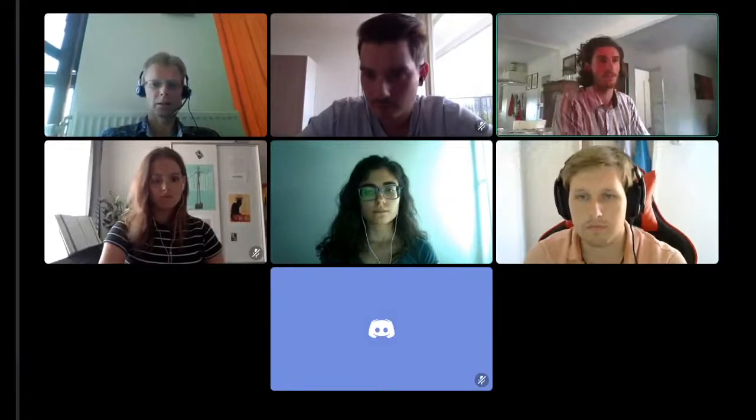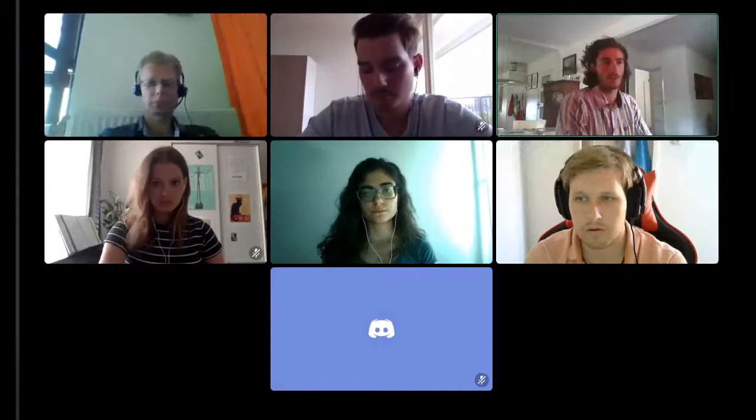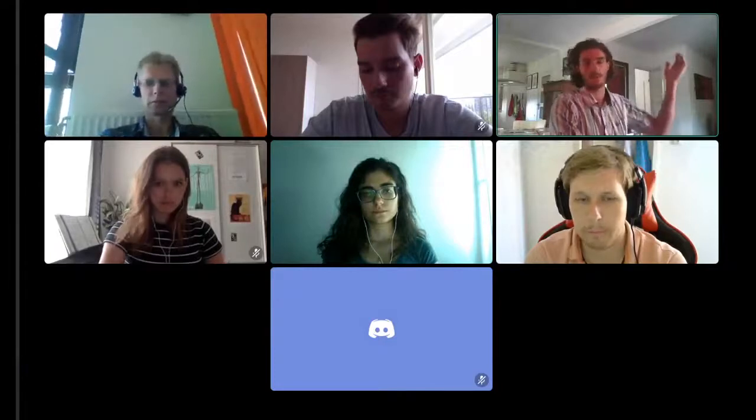Yeah, I can answer that. So in the cross sections that we produce, we write them to an XML file, which is then processed by the Nucleus software. And in that file, you can address at which height the receiver is placed on top of the local ground level. So normally we always do it at 2 meters height, which is the standard. But you can also set it at 6 meters or 10 meters height, and that will give you a different result.